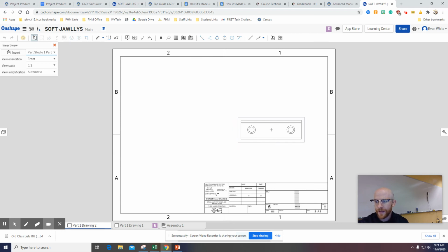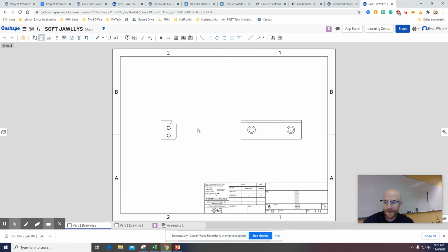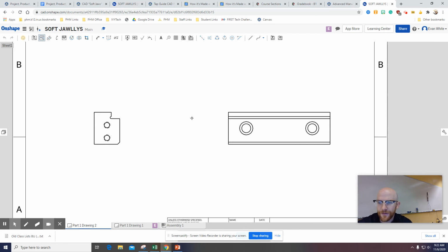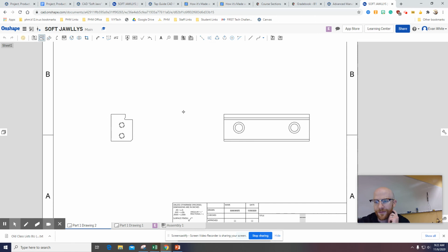So I am going to put the front face over here on this side. And that might be a little different, but remember, we're only doing 2 faces, so it can be over there rather than the bottom left. Typically, in a 4 multi-view drawing, you have your front, the bottom left, above that top view, right side view, and isometric. But in this case, we just have these 2 views.